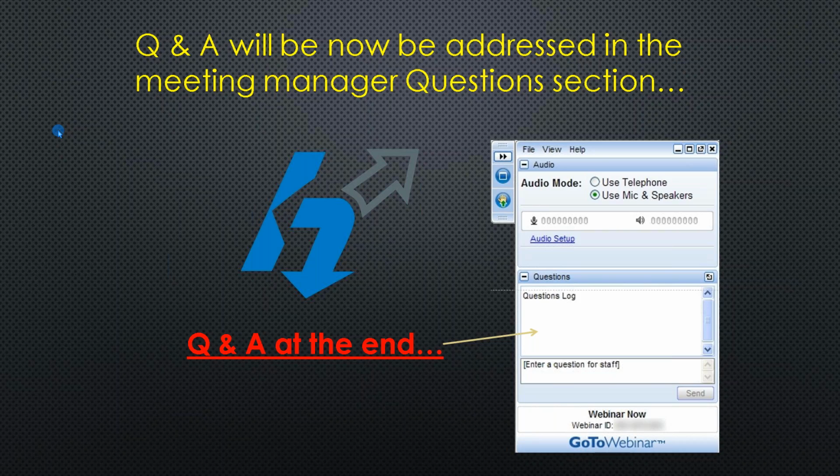Having recently spoken with an actual weld engineer, his recommendation matches the recommendation we've been given for a number of years now: do not include the welds. There's a lot of unknowns that come into a weld situation. For one, even if you use Inventor's weldment environment and build the welds into the model, when you take that into Nastran, those welds disappear.